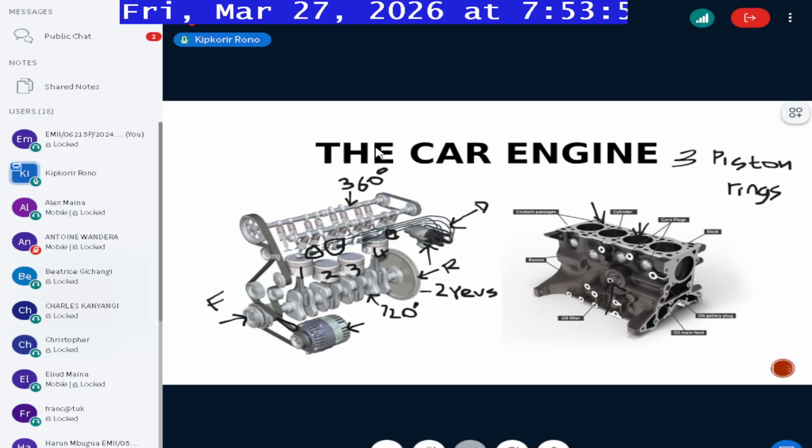If there's a loss of compression, there's usually a high chance that you'll also find some dark deposits around the top part of the piston, called the piston crown. Those dark deposits are usually a pointer that there could be a significant amount of oil leakage into the cylinder. That means in the combustion process, you're combusting not just air and fuel, but also the oil.